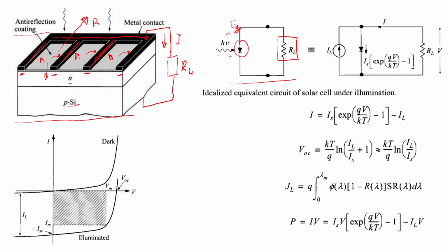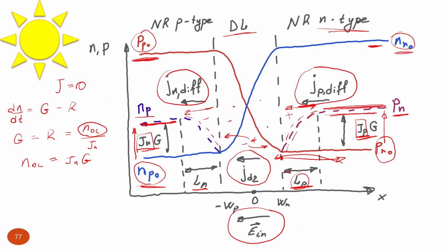So usually we don't show this in such manner. We show the fact that we illuminate the p-n junction with the addition of a photocurrent generator. So that stands for the photocurrent generator in the electrical circuit. It generates photocurrent, which goes partially through the p-n junction as forward current, because under illumination I mentioned that we have forward current, and the load resistor.